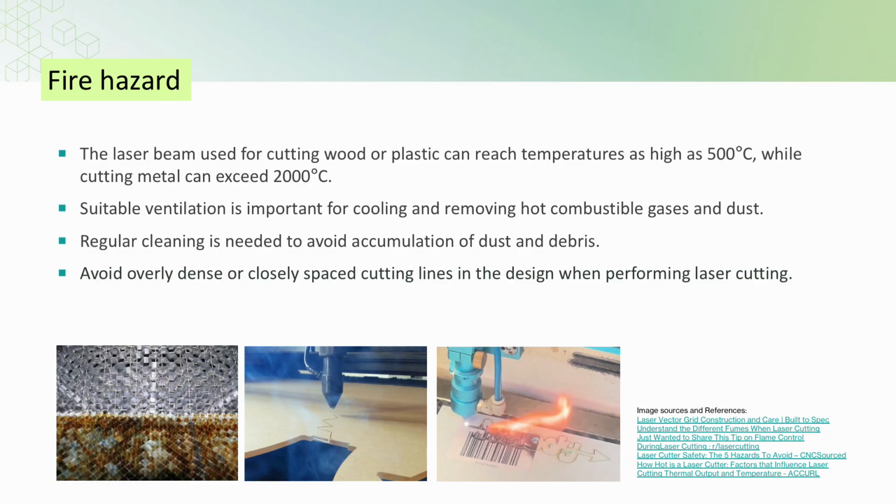About fire hazards, the material being processed by the laser beam can become very hot. Suitable ventilation for cooling and removing the combustible gas and dust generated during laser processing is always needed to minimize fire risk. Regular cleaning to remove accumulation of dust and debris from the chamber is also a good maintenance habit to remove combustible material. Furthermore, too dense or too close cutting lines in the drawing would cause a huge accumulation of heat in a short time and thus should also be avoided.